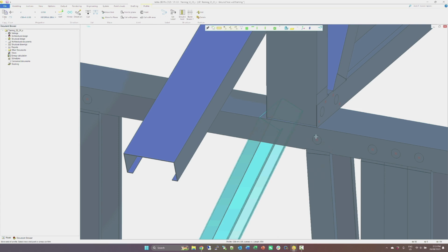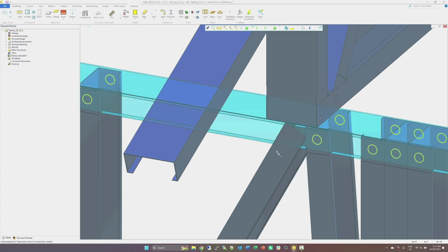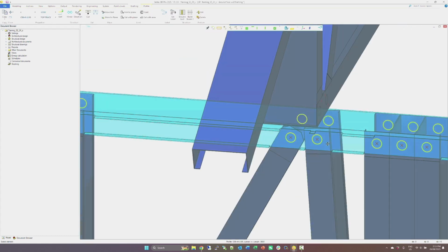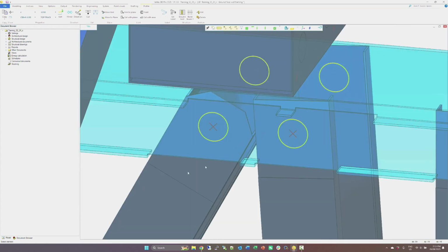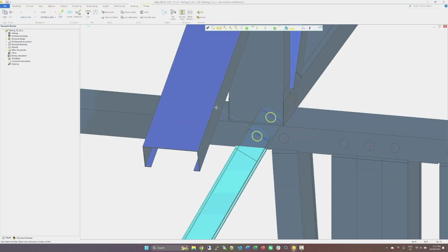Then I will again move this in, so it's 55 mil away from that node. We can check easily, see if they have overlapped. In this case, I'll move it away a bit further, so we'll have a bit more tolerance to work with.